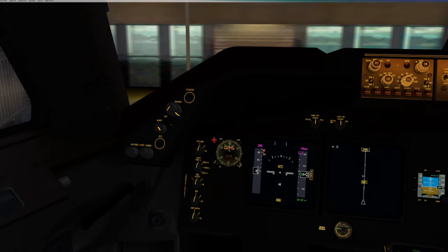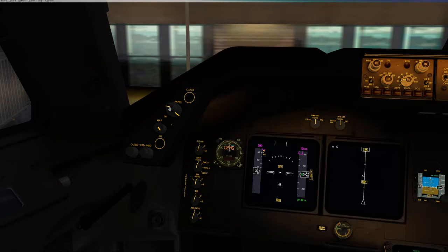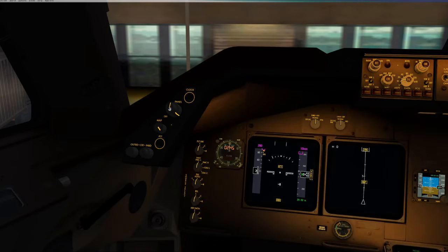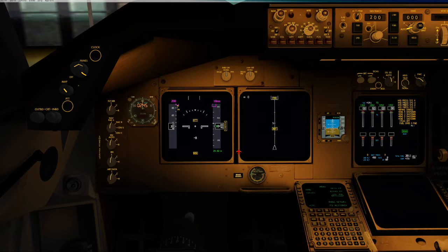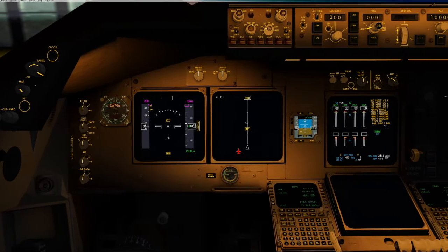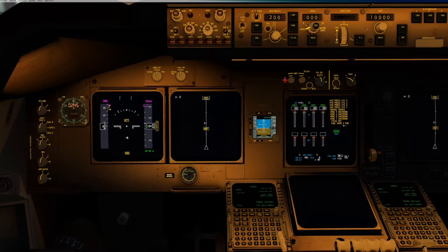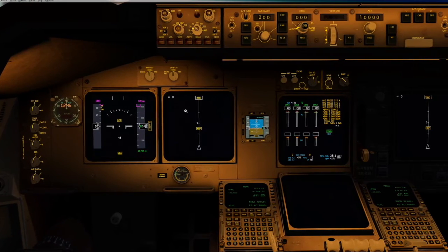And you notice when I rotated that, now I have lighting for my instrument source select switches, my clock, my inboard CRT and lower CRT switches are illuminated. So you've got some panel lights here. Now I'm going to bring on the floodlight portion of that, which is the small inner switch. And notice now we're getting floodlights as well. The floodlights and the panel lights, for the captain, he controls pretty much over to the gear handle. So you can see all these panel lights came on when you turned that light.